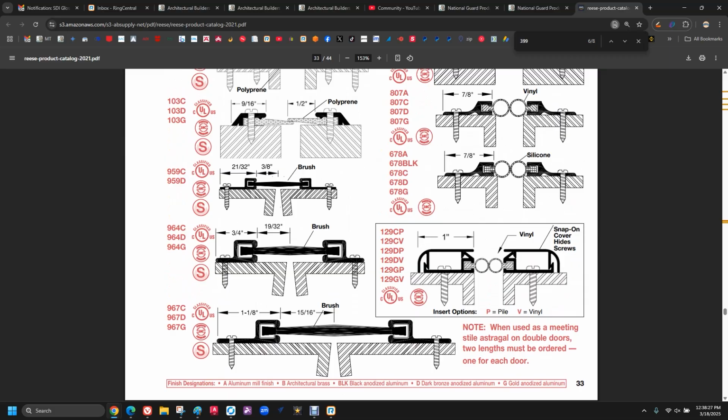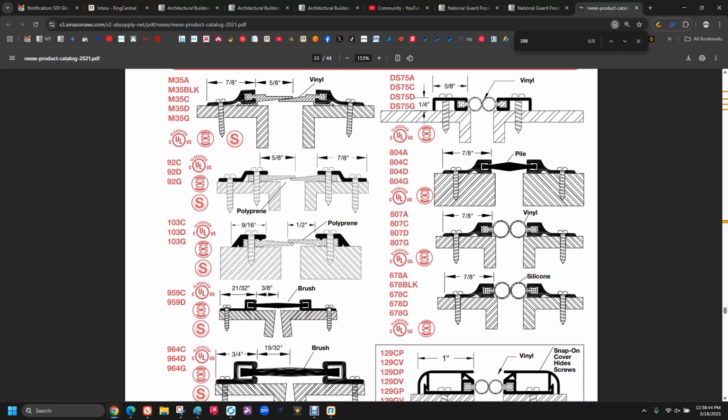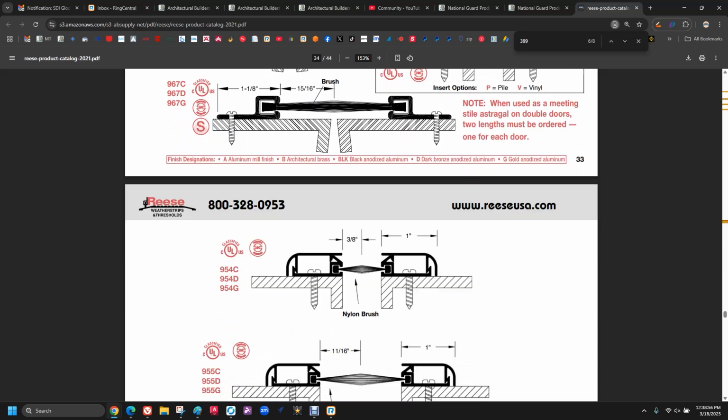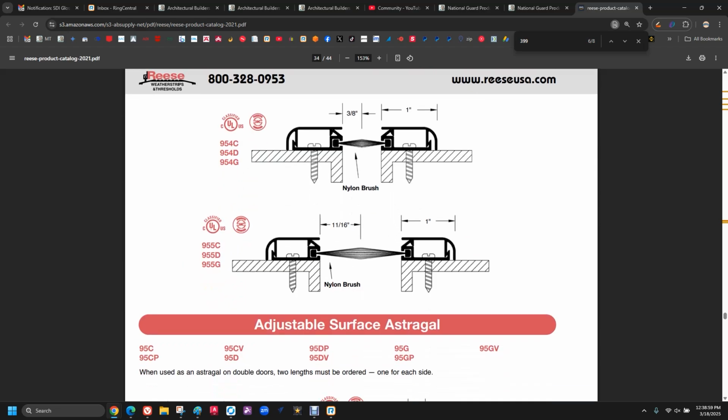Now, one thing that's interesting is you've got aluminum. You've got steel. Hold that retainer. You've got nylon brush. And then you've got the steel screw. And yeah, that steel screw is going to rust. So you might want to consider stainless steel fasteners where you can. Plus, when you drill the hole into the hollow metal door, you've exposed the raw steel. It will rust from there as well. So that's just a fact of life with that stuff. I've had customers complain about it, and I said, listen, I didn't make the world, I just live in it. That's a hollow metal door.